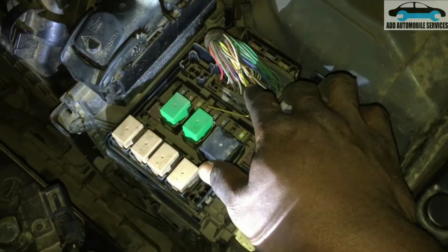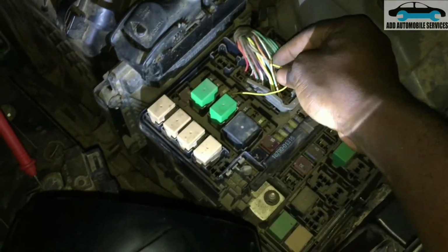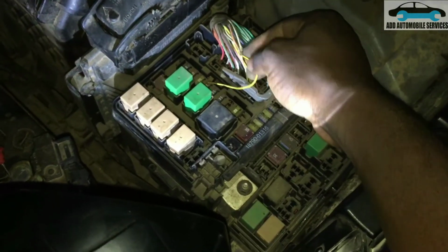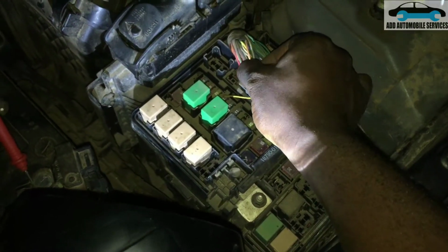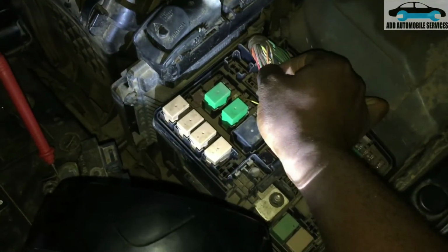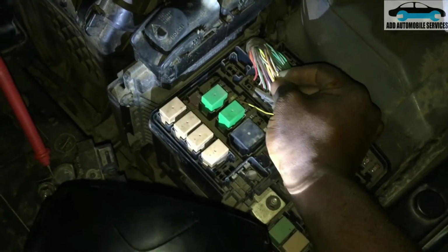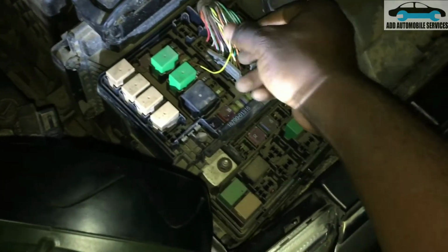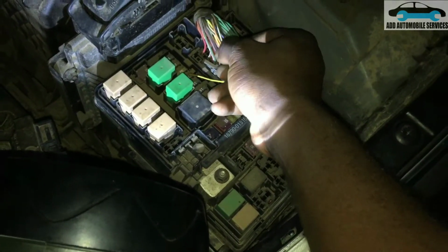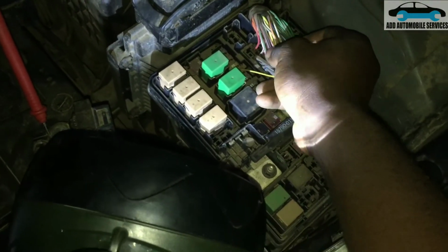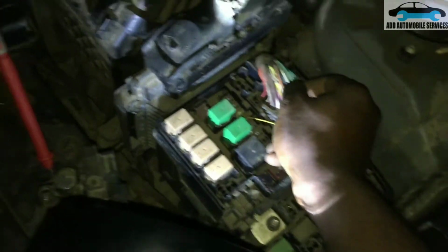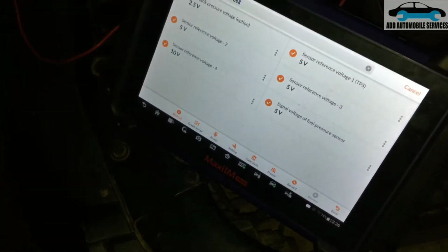So what I'll do now is, this is the yellow wire that they've connected to it, and it's a white wire and I don't know. So this is connector E11. So what I'll do now is I'll disconnect it. I'm sure it is this that's causing the problem, and I don't know why they tapped that wire at that side. The car was towed to my shop.